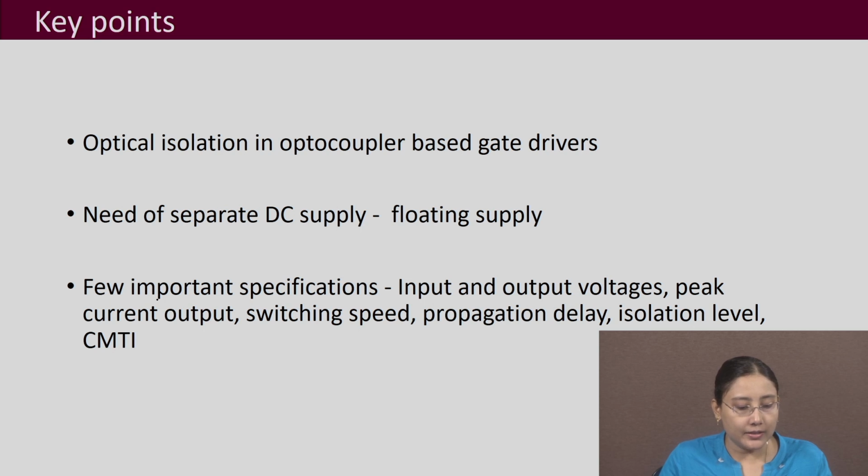And then the other important specifications that you should be looking for are your input and output voltages, peak current output, switching speed, propagation delay, isolation levels, and CMTI.